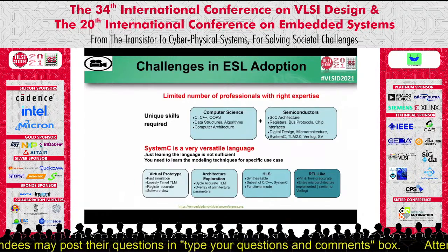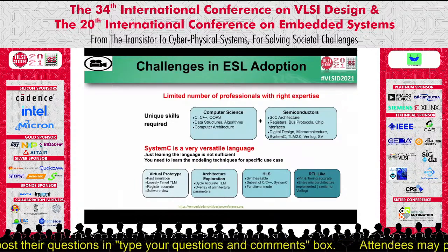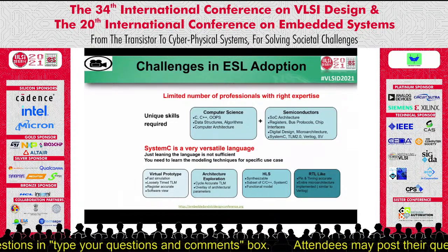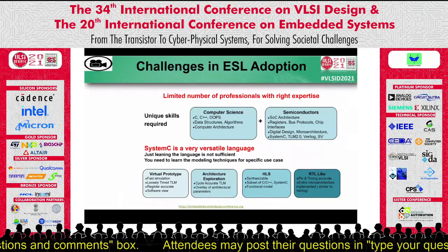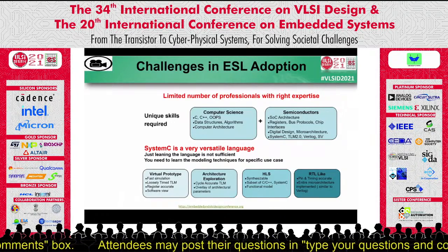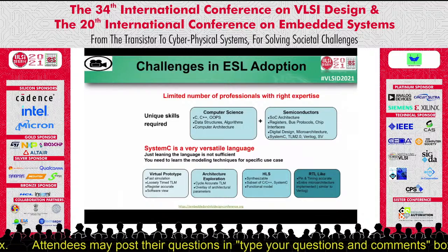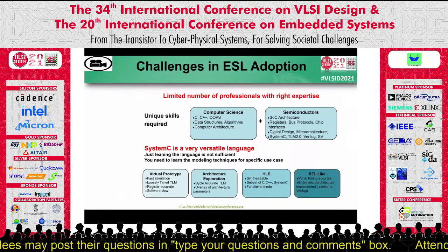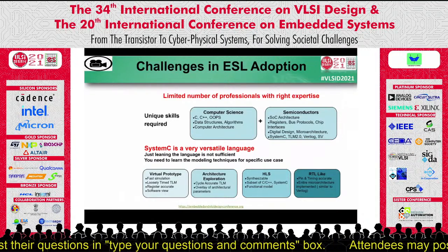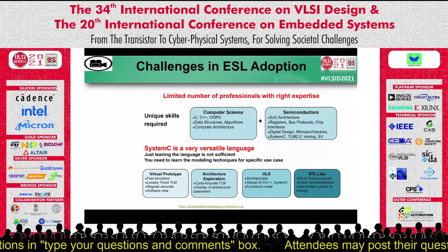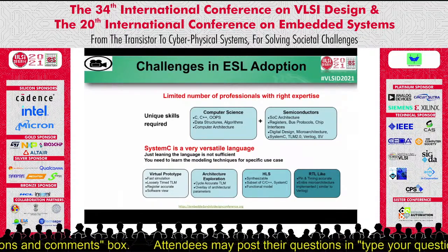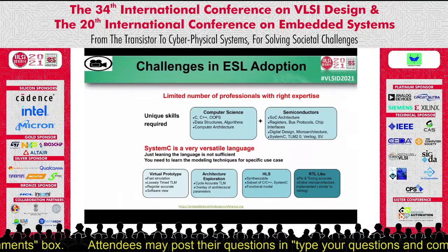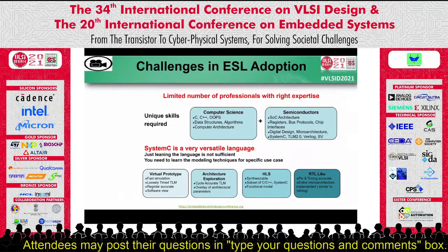Second, SystemC is the language which is at the heart of these ESL flows, and SystemC is a very versatile language. Using SystemC, you can develop models which are as fast as the real hardware and can be used in virtual platforms, or you can develop models like RTL in Verilog, but then these models will be very slow. So just learning the language will not be sufficient. You need to learn the specific technique for developing models for the specific use case.